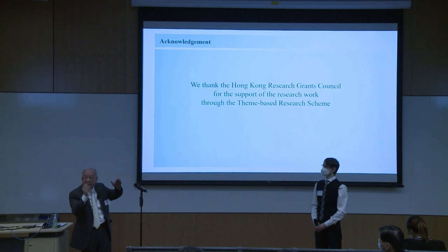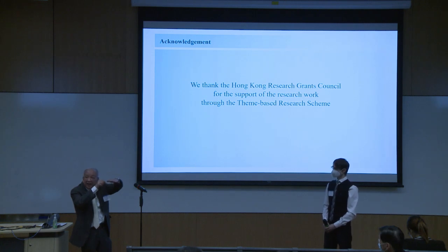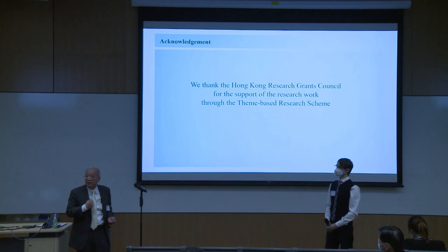So what we did is that we print it like this, okay? But we have a lot of very thin, hairy type of supporting structure that can be detached from the plating platform very easily. And then we can actually use a brush to take off these struts. Therefore, the manufacturer was so surprised that we can have this lens operating at 300 gigahertz.